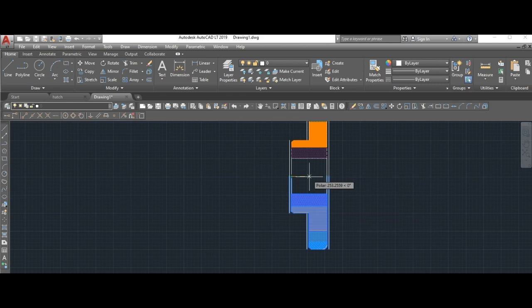You see now what is happening. I press and I click. You can see, and I said erase source object, no. Now you can see I have a perfect shape. Now I can do the hatch in between because it's now a closed object.